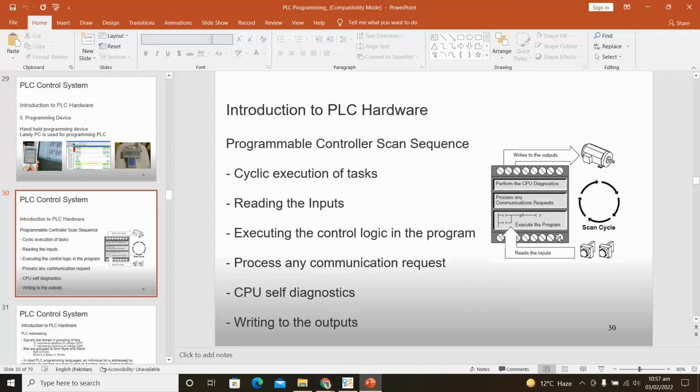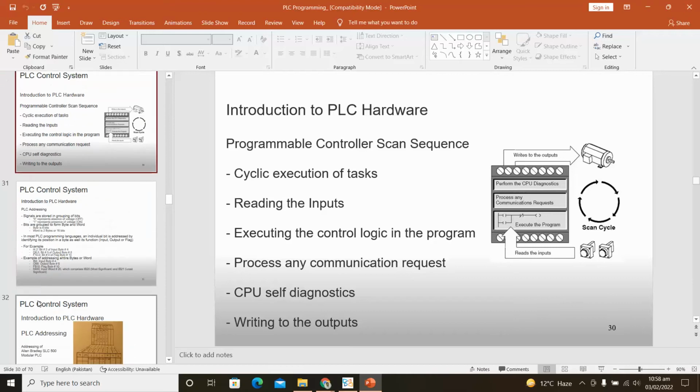extremely fast. It's not that let's say the sensor was supposed to give a 1 here, and at that time you were listening to another sensor, scanning that one, and you missed this one. No, that signal will at least stay there for microseconds or milliseconds. That's still fast enough to scan it. And the device will not even know that there are other devices connected. Every device will get the full attention of the PLC, of the CPU.